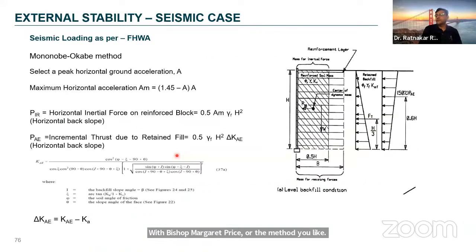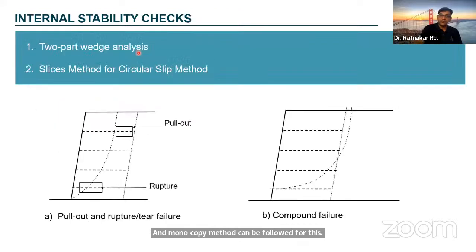Seismic design, I will not much deliberate on it. Professor already mentioned, seismic design is very, very important. And the Mononobe-Okabe method can be followed for this. The details can be studied in FHWA or IS code.